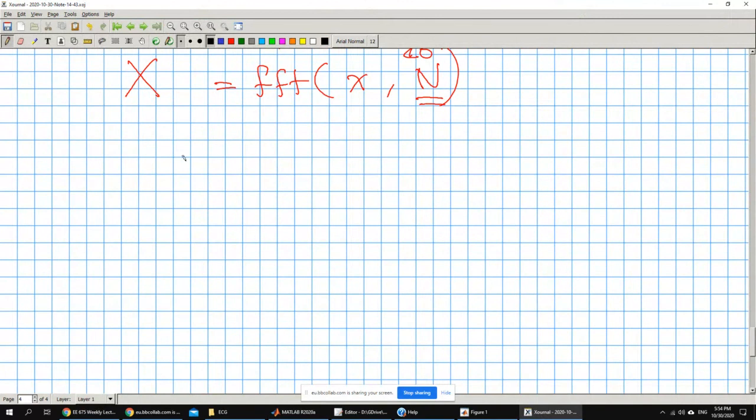Because basically, as you remember, for the Fourier transformation, the FFT, what it does is it gives you the spectrum. It gives you a spectrum that looks like this. Basically, this is from 0 to n-1, for example. Basically, it should look like this, but actually it gives you from 0 to twice pi, not from minus pi to pi. So what you will see is that the DC value is different, and then each one of these values will correspond to another one from here. So this one will correspond to this one here, and so on.